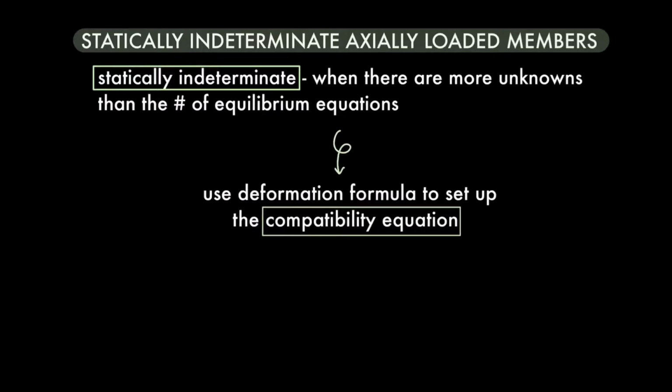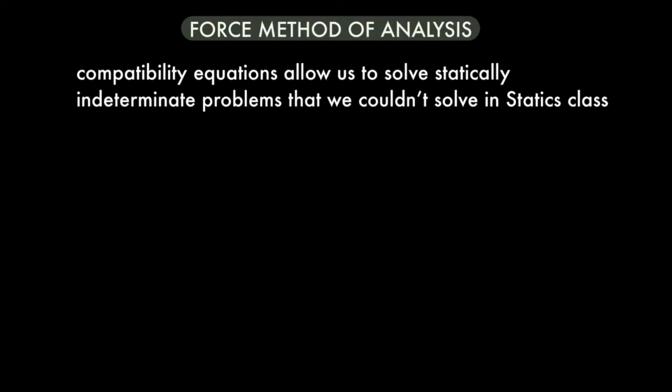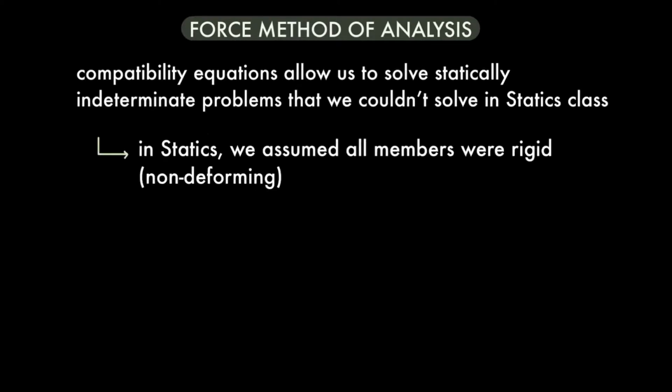In cases of statically indeterminate structures, we need to come up with a fourth equation called the compatibility equation. There's actually no defined formula of compatibility. Instead, we take a look at the load displacement relationship to tell us if and how the bar can deform at its supports. The method we'll use to formulate our compatibility equation is called the force method of analysis.